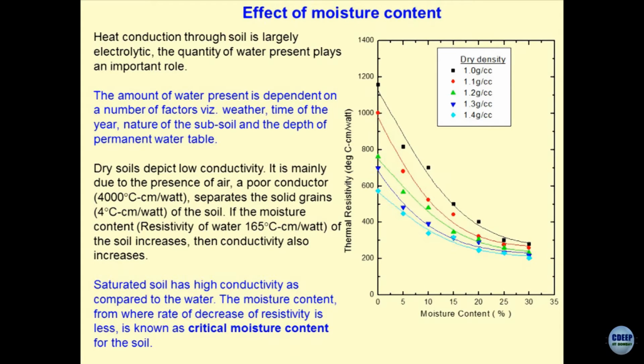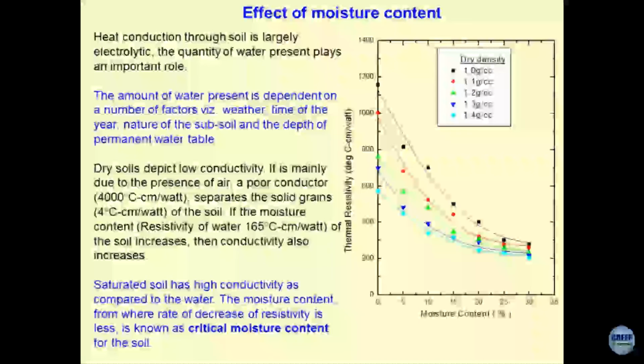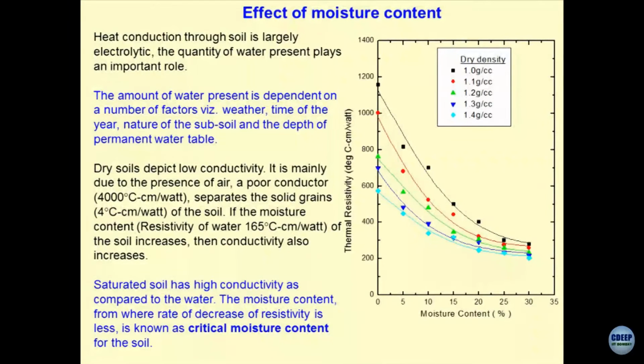And what is done in real life is, either people maintain the moisture by irrigating the structures, or you devise these types of thermal barriers. So, this is becoming a big subject. Most of the thermal power plants which have come up in the recent past require this type of knowledge for designing their buried pipelines and buried cable systems.